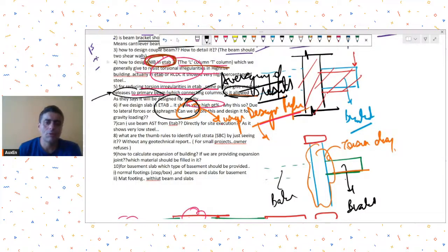Of course, remember that it's FEM software, so you will get reinforcement values for each and every point, and as I told you, at local maxima you may have very high values, but that needs to be averaged out, so you need some understanding for it.